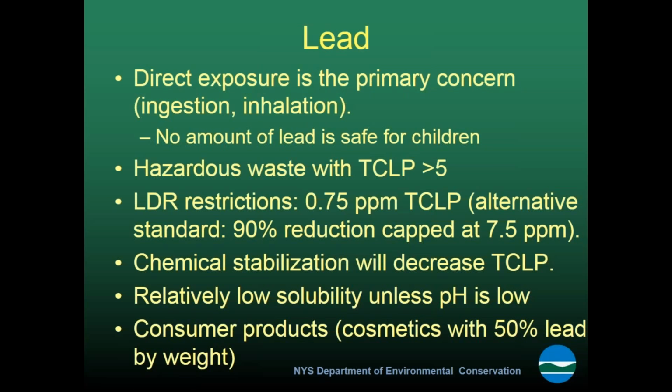Anytime you're handling lead remediation waste that does fail the TCLP for hazardous waste, be aware that chemical stabilization is available, which will decrease that TCLP and which would allow you to eliminate that hazardous characteristic. That's generally very much worth your time and money. It will bring down the overall cost of the remediation project if you can eliminate that hazardous characteristic and manage that as non-hazardous soil. So definitely be aware of chemical stabilization. It's been around for a very long time now and has been proven to be effective.